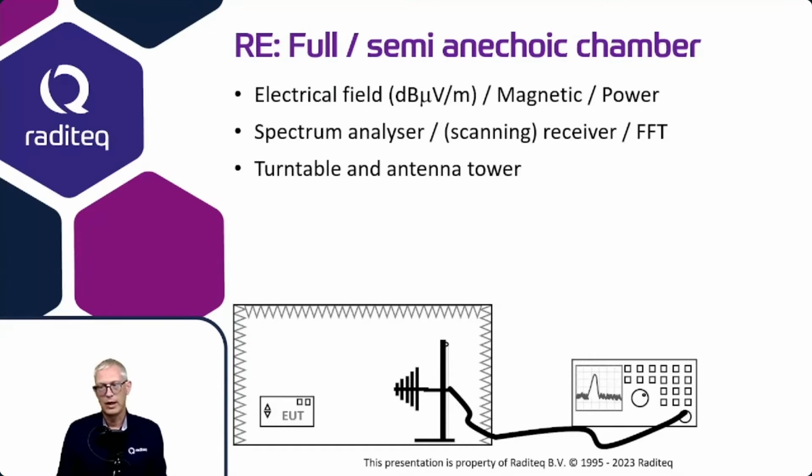It's easy to configure, and also, of course, the units can be adjusted to present it in volts per meter or in another unit, or in dB picotesla, for example, like that. We do support spectrum analyzer mode, receiver mode, and scanning receiver mode, and modern receivers very often have an FFT or a time domain mode. All these different modes of the analyzer can be controlled with RadiMation, and it's up to the preference of the end user. We can support the mode that's preferred.